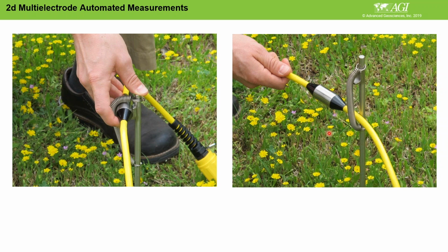Some people just use alligator clips, putting the electrode on the ground and clipping onto it. But what happens if I put it on the ground here, and then use a spare extension wire with alligator clips, connecting to the ground from here and also from here? That means I am doubling up my current injection.